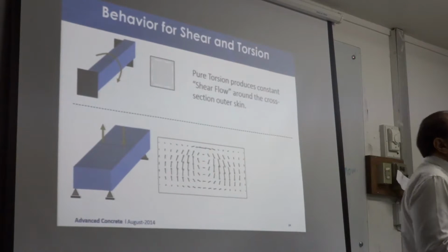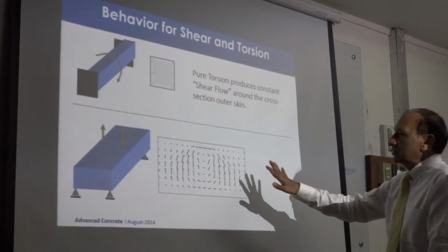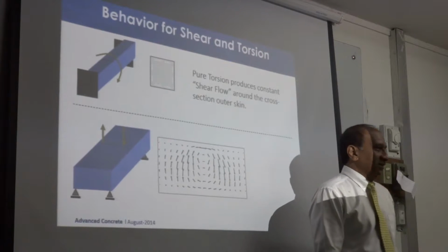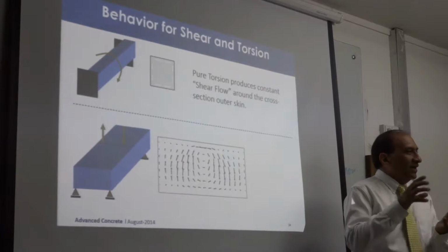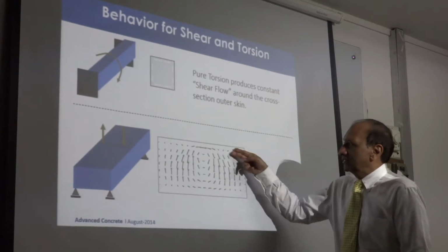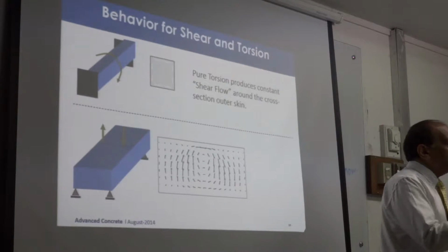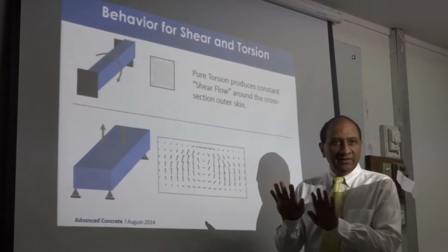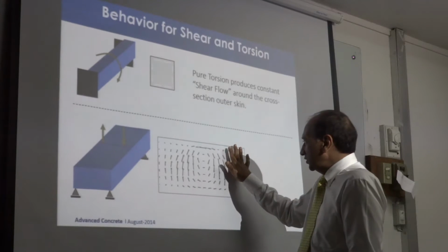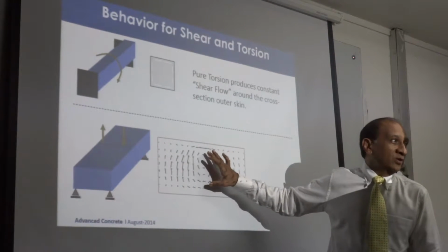So the cost was so high because most of the reinforcement was coming from shear, very small from torsion, because torsion was not that big. But when they combined the reinforcement for shear and torsion, they put it along this section. We just asked them to separate the shear and torsion reinforcement, put the shear reinforcement only vertical, and horizontal should only be torsion, which is very small.